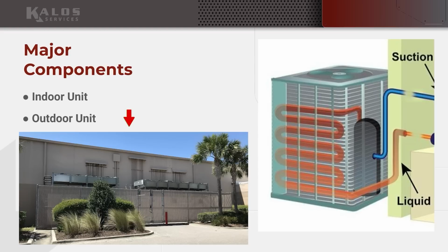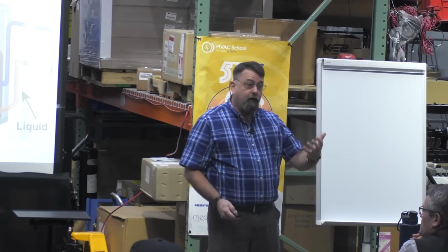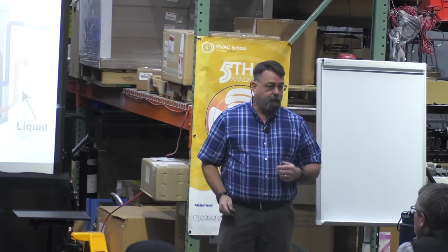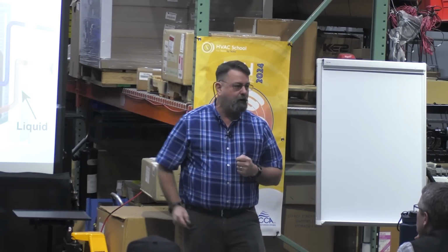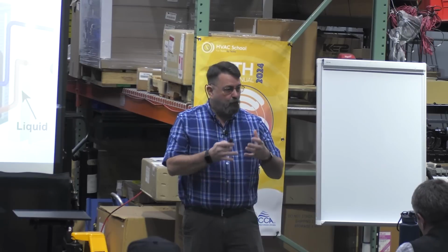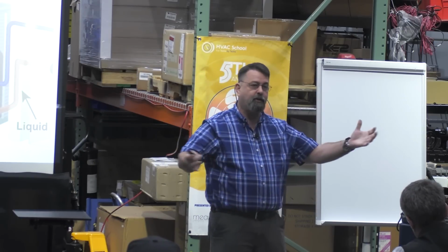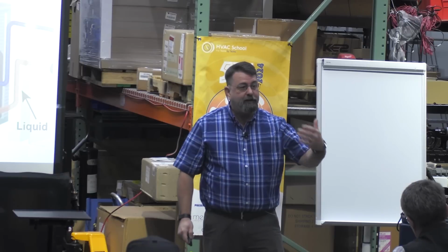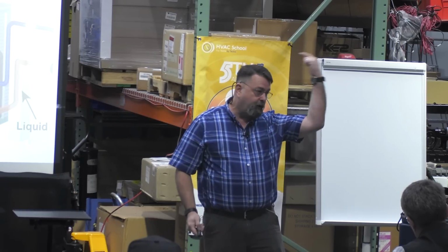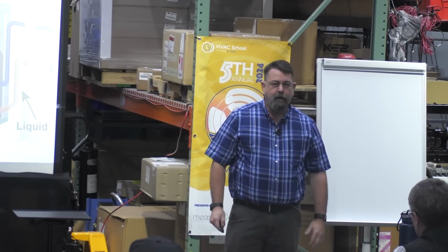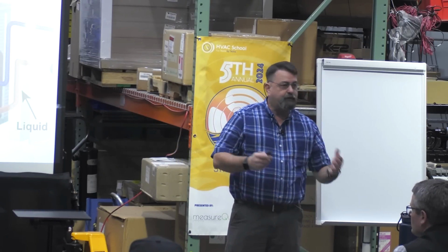This particular one that I'm showing you a picture of here actually has two racks. It's one rack house. It has two separate racks inside. Then you can see on top, I've got my condensers, right? That's kind of a typical setup. Another version you might hear of is the motor room, okay? We may have exactly the same equipment, but it's actually in a room inside the store. You walk in, you open the door, turn on the light, there's all your compressors. The only thing that'll be different there, my condenser will be on the roof, right above it, okay? So that's a rack house versus a motor room.